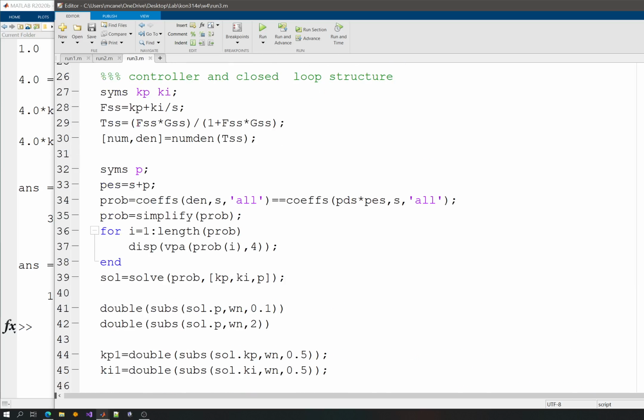Now, since I have a PI controller, or starting with the PI controller or PD controller, we will add zeros to the system. We are not concerned only with, or we are not just changing the poles or adding poles. We are also somehow adding zeros, which might be a good idea, which might not be a good idea. It depends on the situation. And most of the time, the zeros will change what we are trying to do, because